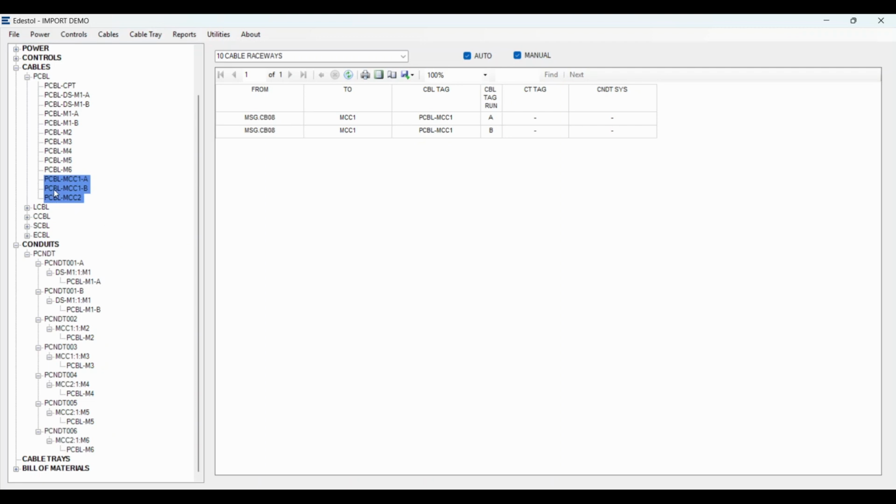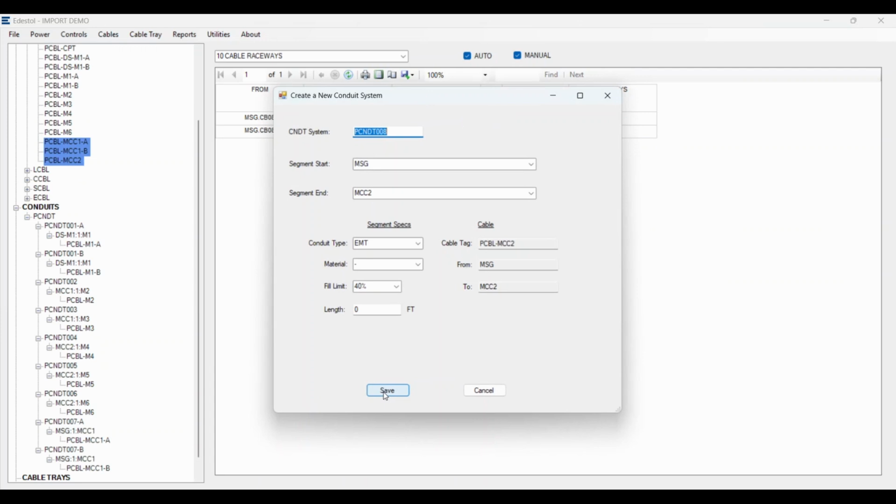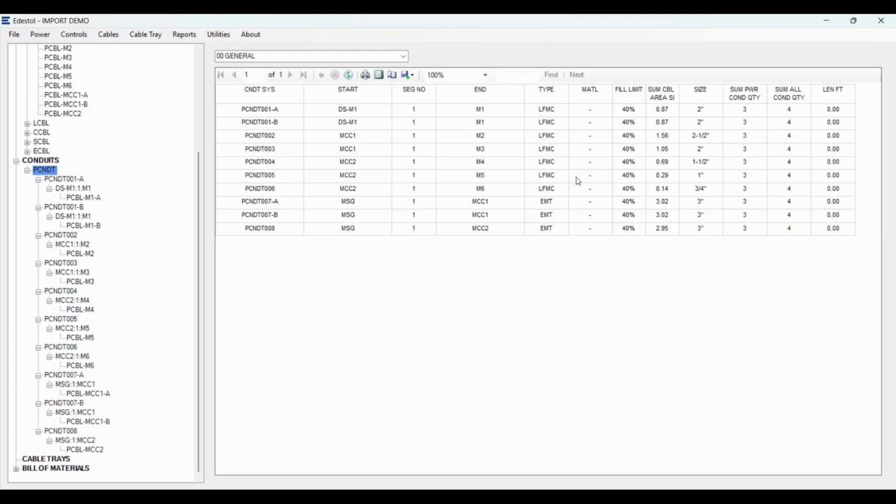All right, you can take them down and just drop them in conduit. It'll put it in the appropriate P conduit or L conduit, creates whatever. And see, you can see it's creating another parallel run. This is the feeders from the main switch gear to the MCC1. Okay, this is your feeders. So there you go. And then we did 8, and you got 9 down there. So now you've got all the way down to 7, 8. Yep, just 2 different ones. So let's go back to our P cables. So that's the way you do that.